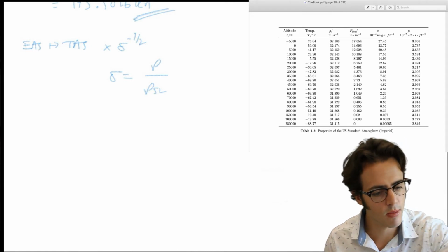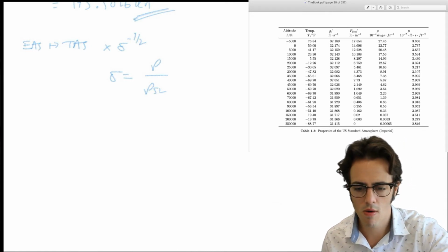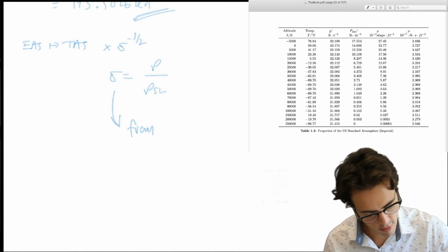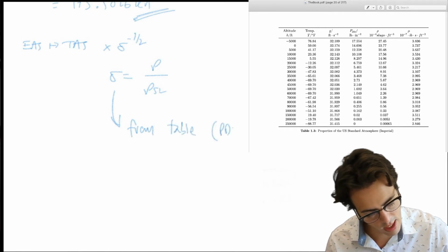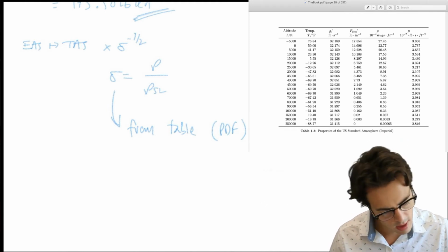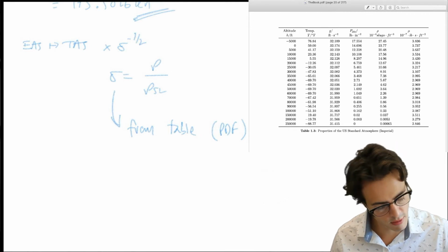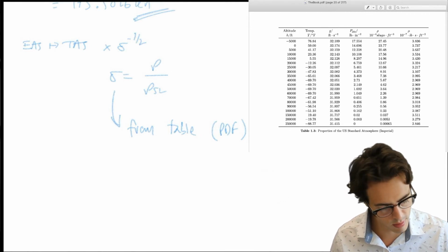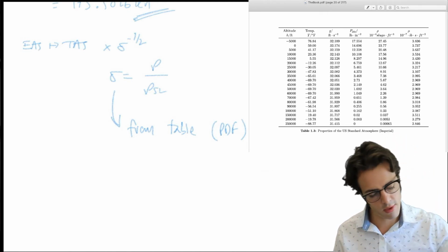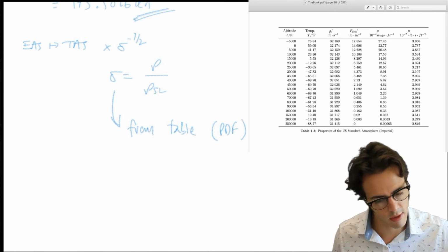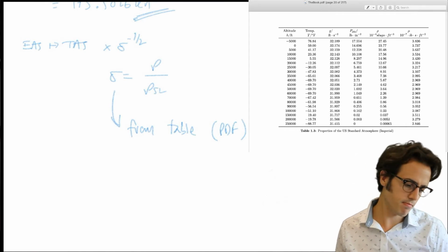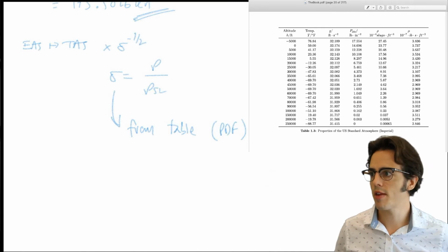Let me just find what I worked it out to be. I'm not going to go through all of these again. So sigma from the table, if you're looking at the PDF notes: if we get the two densities, you'll do a two-dimensional interpolation just as I've done before. You'll end up with 6.021 divided by 23.77. I'm using those densities in slugs, and I've not bothered to multiply them by 10 to the minus 4. You'll end up with a sigma value of 0.2533, using all of those values from the table.